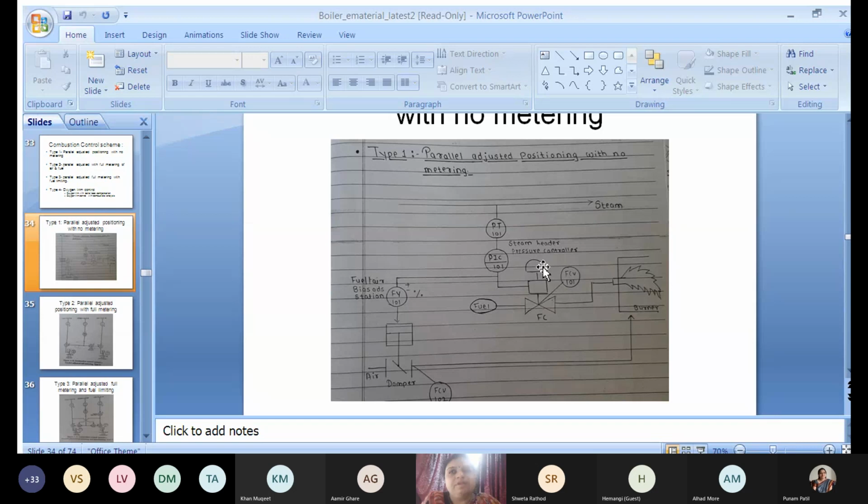Correct. If the controller is direct acting, you can make your control valve actuator reverse acting. For a higher signal, it will respond in the opposite way, that is, it will close. For a lower signal, it will open, if it is air to open, air to close accordingly. So you have to select the components in that way.